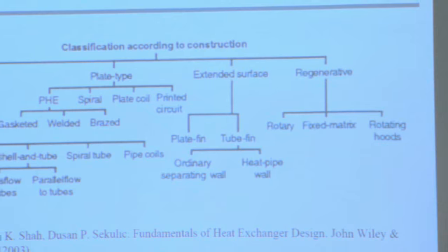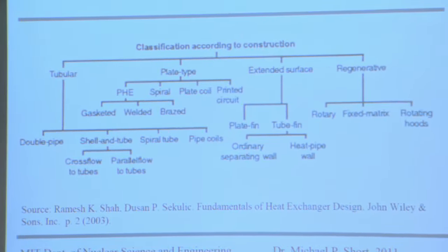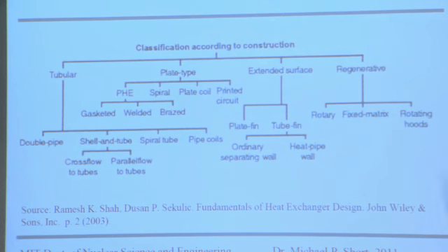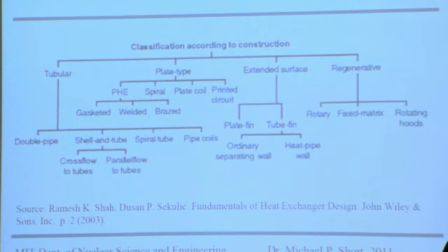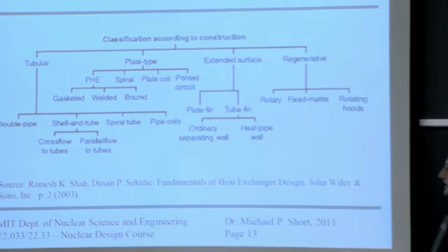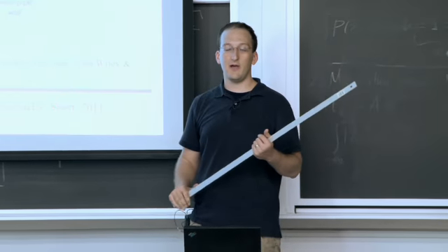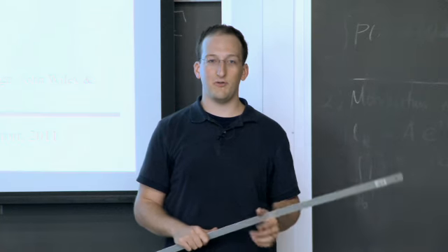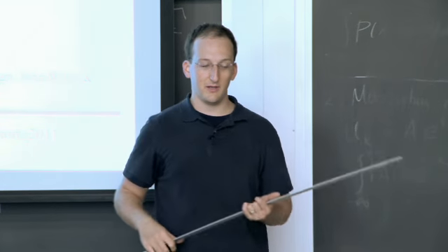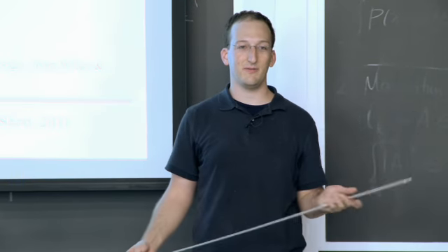As for flow configurations, there are tubular heat exchangers, like the 2 that I brought in here. There's plate type, spiral, printed circuit, all sorts of crazy things. They all have their pluses and minuses. The nice thing about tubular heat exchangers is they offer nice cylindrical flow channels. They're a fairly low pressure drop unless your tubes get really, really thin. They are getting kind of thin here, but there's a 40 horsepower motor behind the fluid there, so it's not so bad.